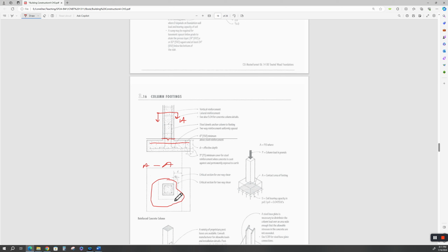There's your reinforcement steel. You may get by with just 4. You may have a lot more depending on how loaded the column is and what the American Concrete Institute code says after you do your calculations. Again, this is not a structural engineering course. And then these are ties that hold the column steel together. All right.